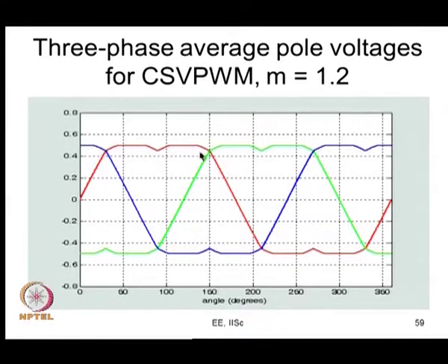Whereas, you take here R phase is switching, Y phase is also switching and B phase is also switching. So, these are places where all the 3 phases are switching and therefore, the 0 state is also getting applied, though the duration of application of 0 state would be lower now than it was during linear modulation. So, here you find all the 3 are applied.